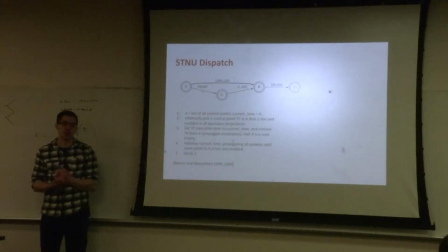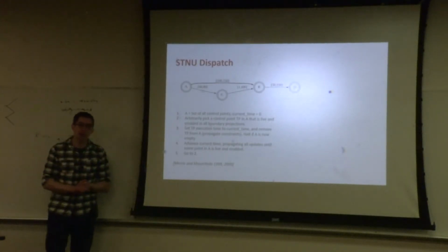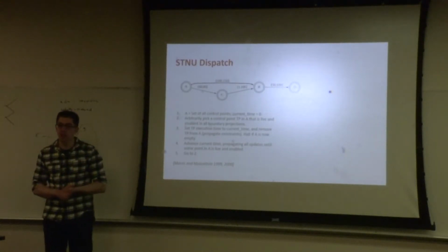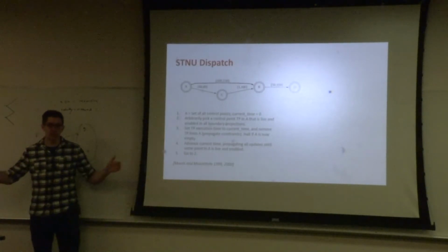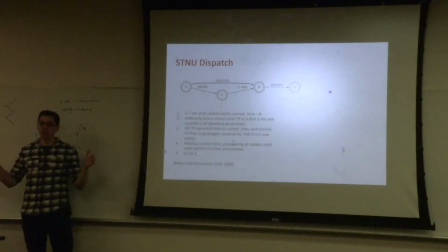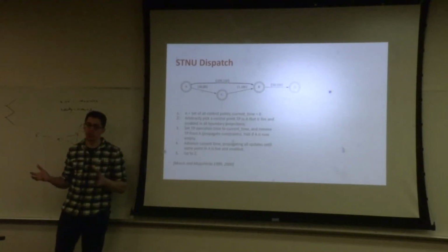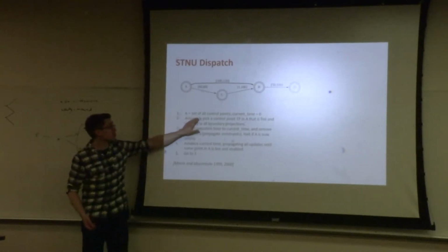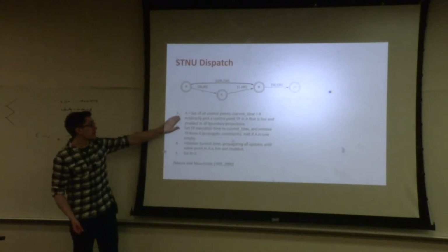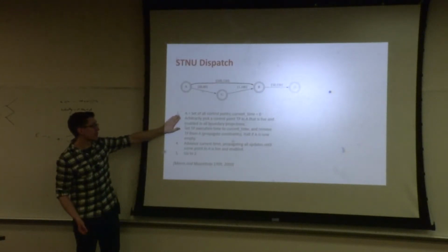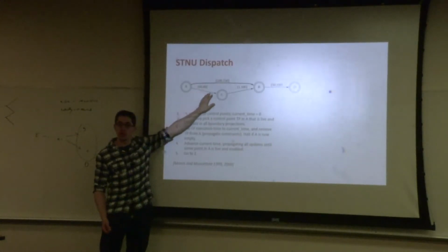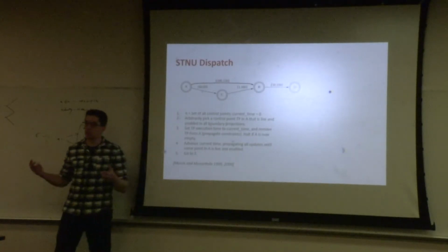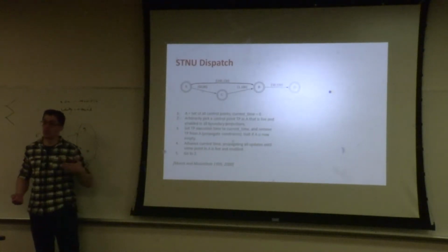When I say to the robot, go to waypoint A, I know that it's going to try go there. My PDDL model says that it's going to take 136.44 seconds to get there. In the real world, it's not going to take that. It's going to take some time to get there between an upper and lower bound, which I might be able to estimate. This algorithm, given the set of all the control points and the current time, picks a control point that is live, that is, it's enabled by all of its incoming edges. The method we use to pick it is we just pick whichever one is live and first in the plan that was produced by the planner.